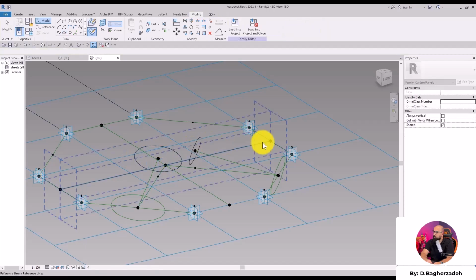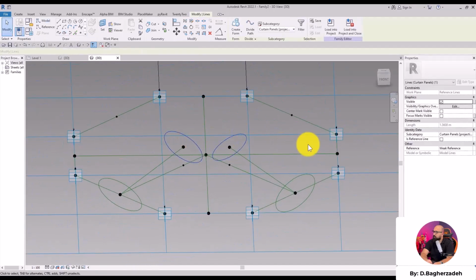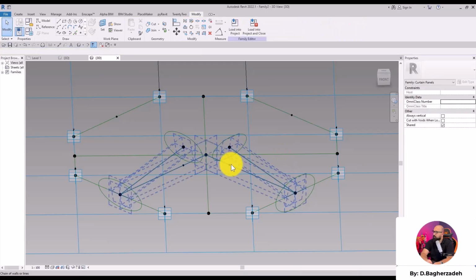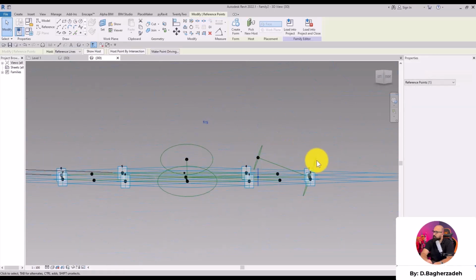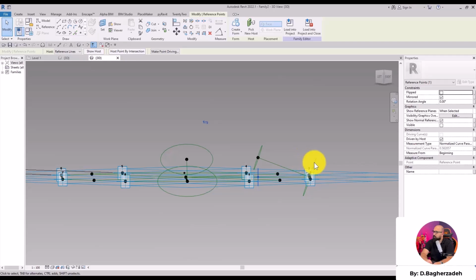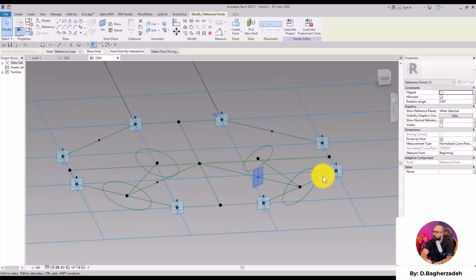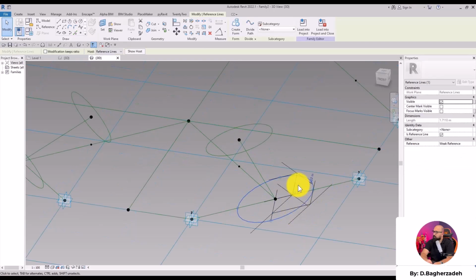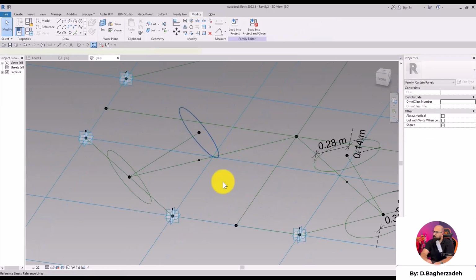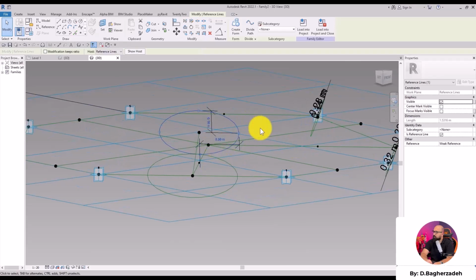All right. Now, select these this time and convert them into references. Now, guys, if I try moving these or actually changing the normalize, as you can see, everything works correctly. And also, as I mentioned earlier, a few seconds ago, the sketches are completely parallel. Now, guys, regarding these sketches, or, well, these ellipses, let me reduce the scale here. Regarding the sketches, we need to set dimensions for them as well.